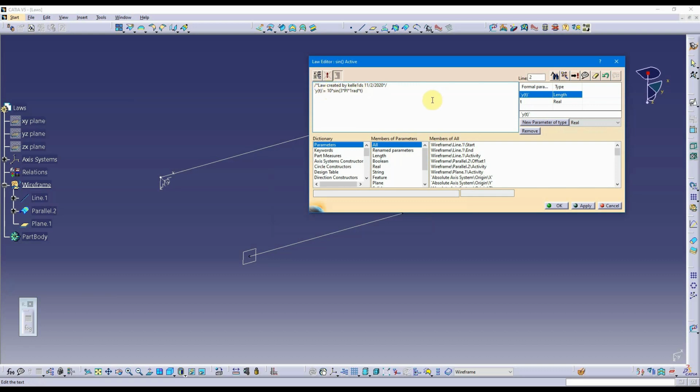So I've got to be very intentional about making sure of that. Notice I just attach the millimeter unit to the 10, which works as well, and I'm not getting any messages. If I took out the rad, it would be the same thing. It would say in no uncertain terms, you're supposed to have an angular value. If I took out the rad, it's just a real number then. So CATIA is going to yell at me. Make sure you get your units right.